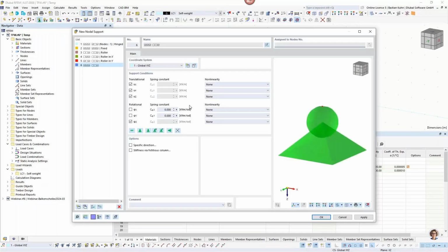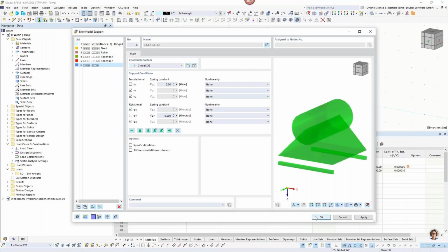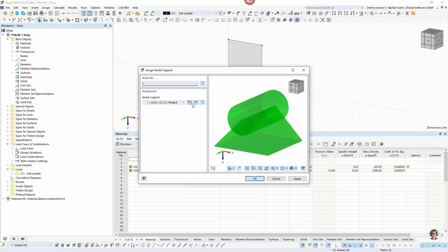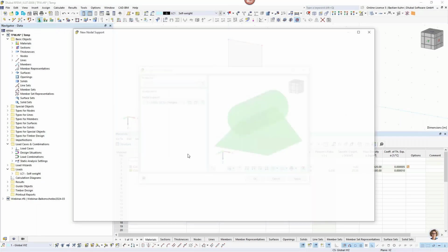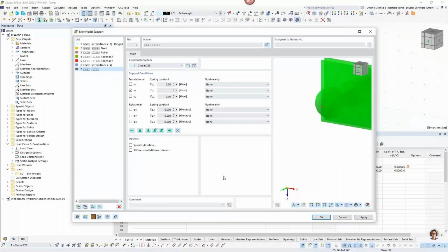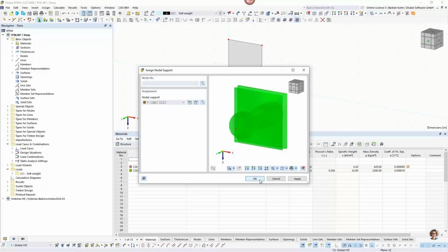In the bigger model that I'm going to do just after this simple model, of course, you would do a complete support underneath the wall. That's for sure. It's just for this first example here. So this one moving, okay, and so that it's not flipping outside of the plane in Y direction, I will define the translational degree of freedom in UY direction.